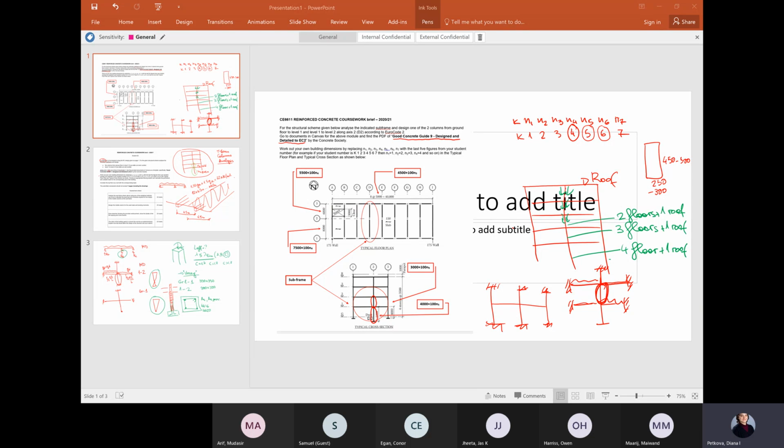So your K1 and K2, if the beams are the same size at the two ends of the column, if the dimensions of the beams don't change, your K1 and K2 should be the same, and your effective length should be between the full length of the element and about 50% of the length of the element. For that calculation, you can take the beam as rectangular, by the way, rather than T-beam, because with the T-beam it will become a bit more complicated.